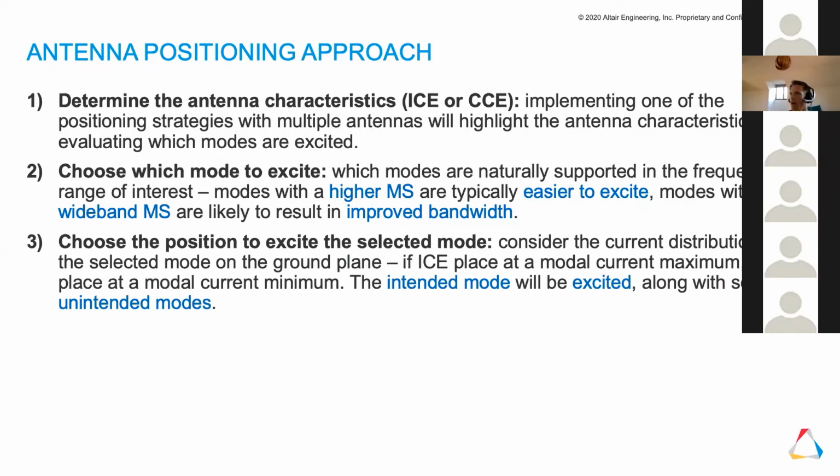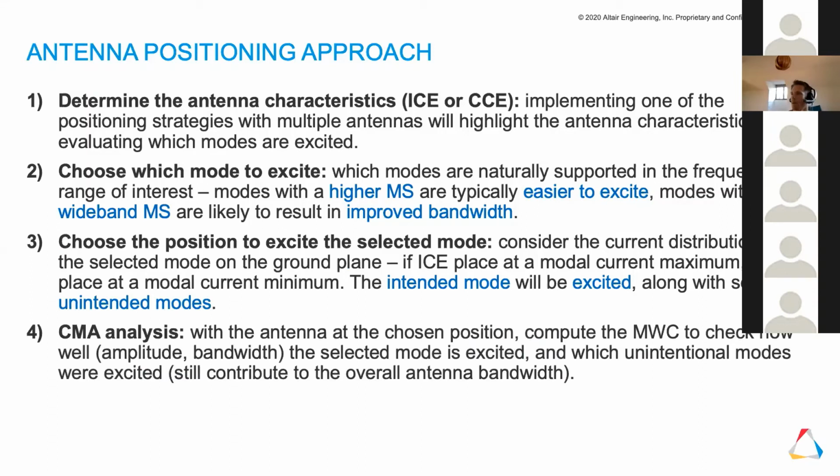So then, based on our positioning strategy, we know that for inductive elements, we place these at the modal current maxima, and conversely for capacitive elements, we place these at the current minimum. And what we expect to happen then is we will excite the intended mode. However, at the same time, we expect to excite these unintended modes.